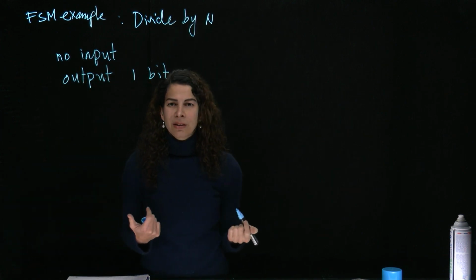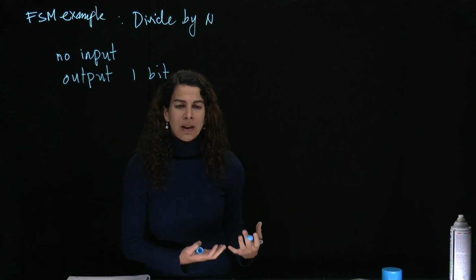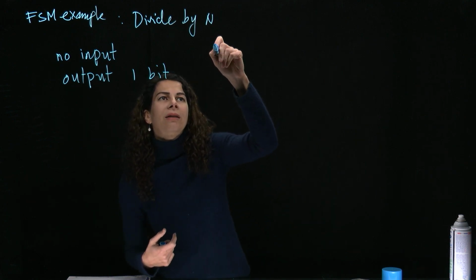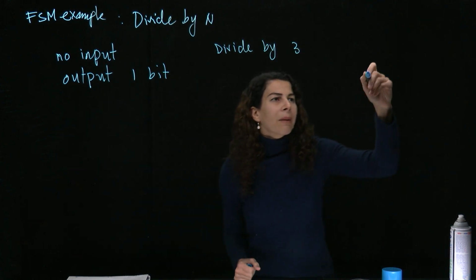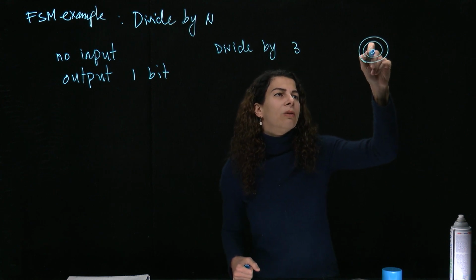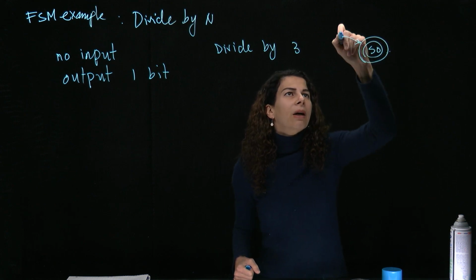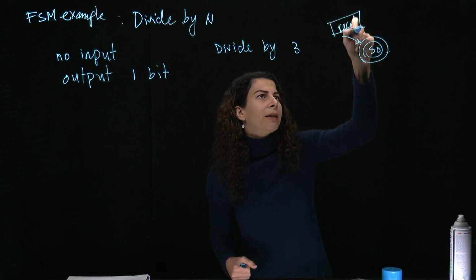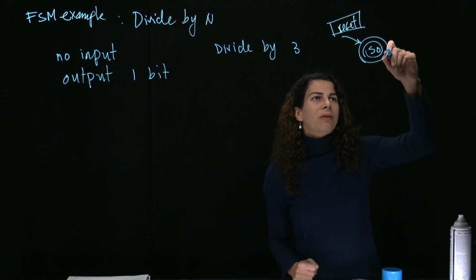Let's go through an example in SystemVerilog of how we express this and tell the hardware design language how this looks. For that reason, let's just focus on a simple divide by 3 example. Let's design a simple finite state machine. This is a reset state S0, where we come and remember, it's a good practice to always have a reset state for your finite state machine. Otherwise, you may get stuck in a loop that goes forever, and that's not recommended.